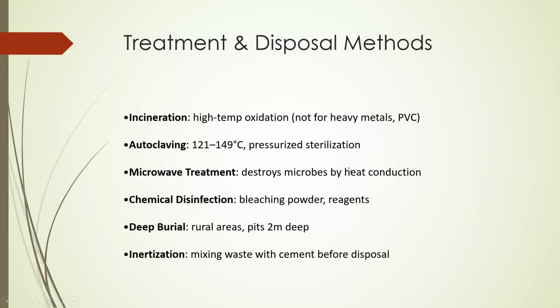This microwave treatment uses a frequency and wavelength of 2450 megahertz and 12.24 centimeters respectively for the destruction of microorganisms. The infectious contaminants in water with biomedical waste are destroyed by heat conduction when it is rapidly heated by the microwaves. By bacteriological and biological tests, the efficiency of microwave disinfection is ensured regularly.